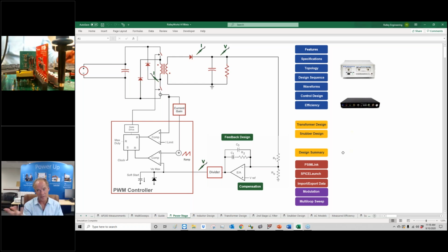But yeah, all of us, we have to do multiple output flybacks. Lots of the app notes that you see out there are not designed for good cross-regulation. They're designed for other things like different EMI signatures. Okay, so a lot of flyback app notes I see, they are not the way I would wind it. And there's too much there to get into in this session. We spend quite a long time with that in our workshop. We have a couple of slides dealing with that, talking about that in detail. How you can move the windings and get different cross-regulation on outputs. Anything else?